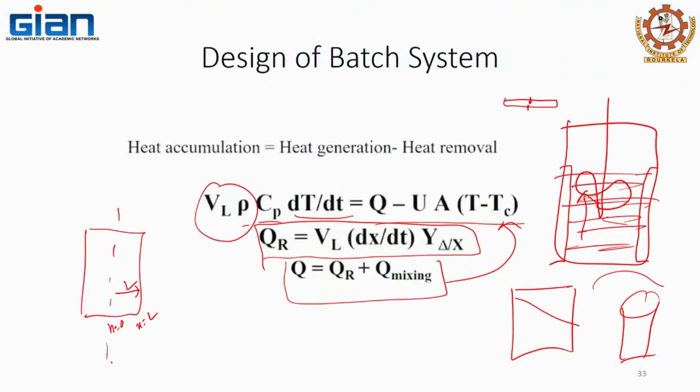Now, as you increase the size of the fermenter, you are increasing the surface area, right? As in a cylinder, like in a slab, the heat transfer is linear. In a cylinder, the heat transfer is not linear, it is parabolic because of an increase in the area, in the radius. So, the surface area keeps on increasing, the heat transfer, the Q will keep on increasing. In this case, how will that impact?